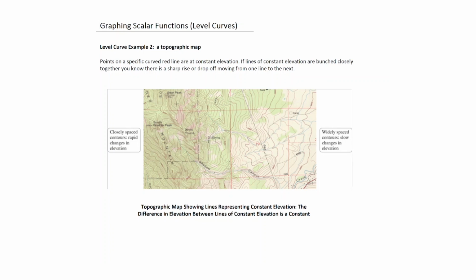So here's an example, for instance, that geologists would use. So you see all these various lines here. Each one of these lines represents a constant value of elevation. All right? And they're typically equidistant. So like maybe 100 meters apart, for example. So if you look at this map, there's something interesting. You notice a lot of lines basically in this area. And they're all suddenly compressed and then suddenly widen out. So this would indicate that this is a side of a mountain. Okay, it's either going up or down. You'd have to know what the values of these are to know that. But this obviously is something steep, and out here it looks like it's relatively flat.